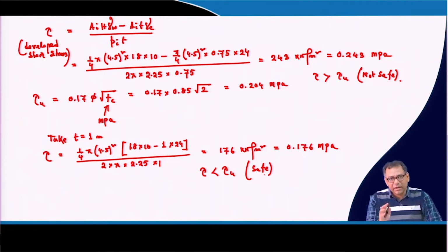So, there will be a shear between this seal concrete and the shaft. So, that is why we are checking that shear stress here, and there will be buoyancy also that we have already checked. So, these two checks we have to do, and then based on that we provide the thickness of that bottom seal.